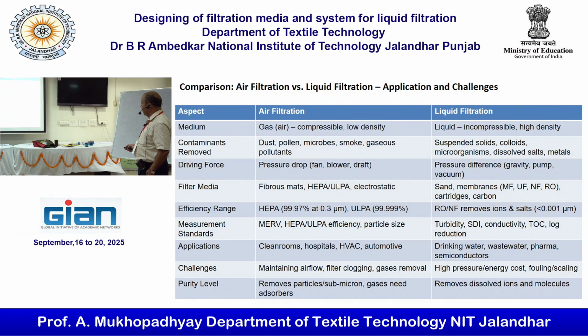The challenges: maintaining airflow is a challenge for air filtration, filter clogging is also a problem, and gaseous removal is also a challenge for air filtration. In liquid filtration, high pressure, energy cost and fouling are the problems. A similar problem is there in liquid filtration: the life of the filter media depends on how the clogging takes place, whether the pores get blocked or not.